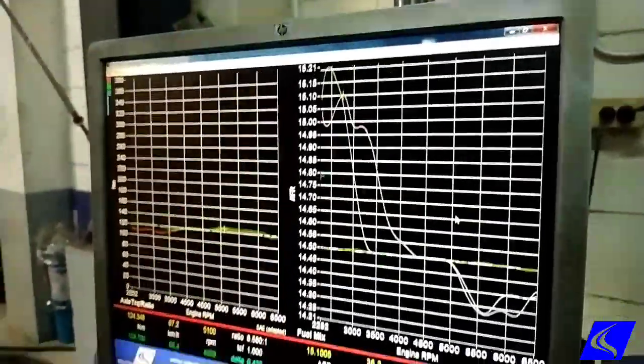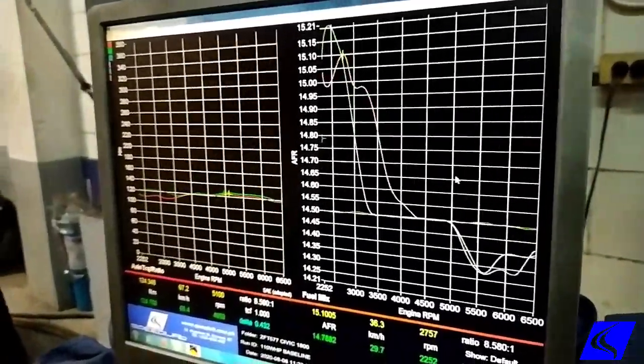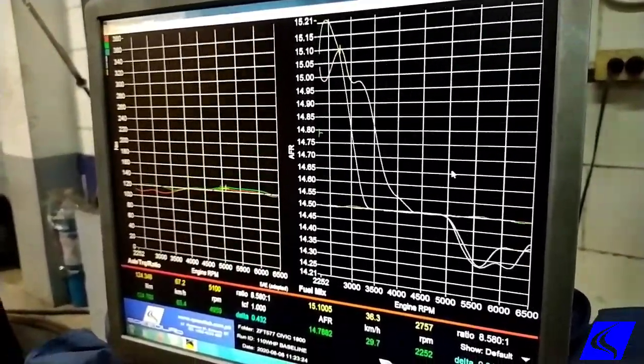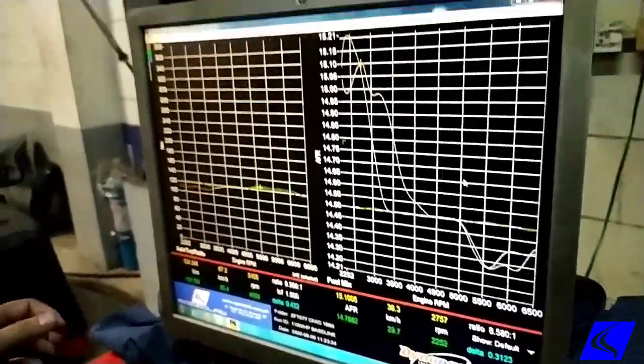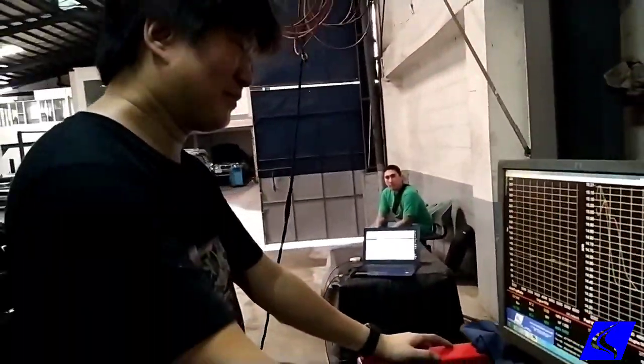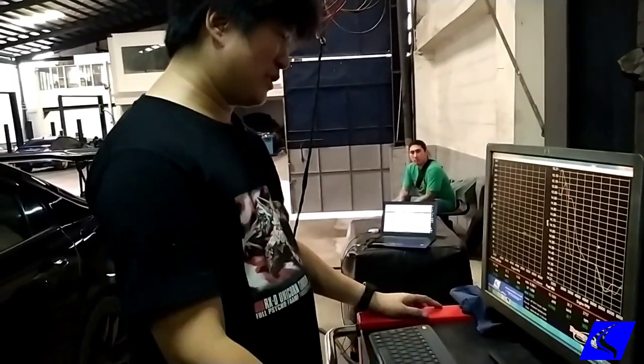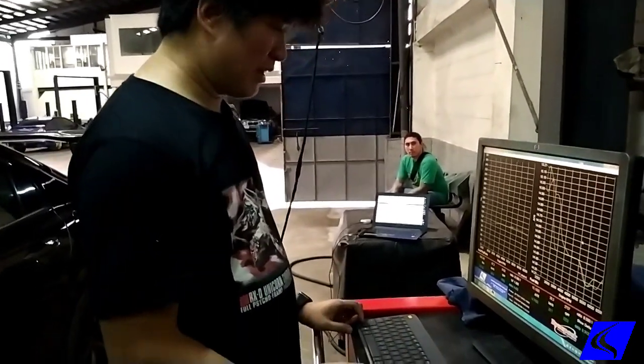So yeah, that's caused by the setup of the exhaust. That's too big. Sana malaking tubo, it's 2.5 inches. That's the wrong size. Okay, we can proceed to tuning now, because now we know what we're dealing with.